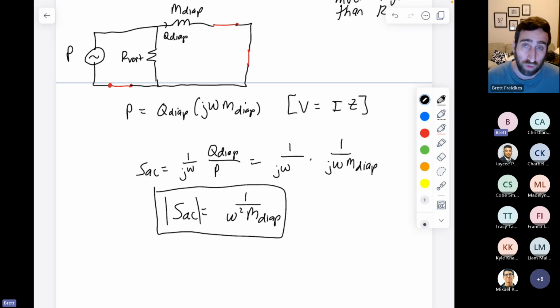Or if you just have a single pole, it's negative 20 decibels per decade. This situation mirrors that because we have omega squared, and that leads to a very rapid drop off in sensitivity because the mass is so overwhelmingly heavy. And due to its inertia at such a high frequency, we cannot get it to move sufficiently to create a meaningful output, let's say an electrical output.